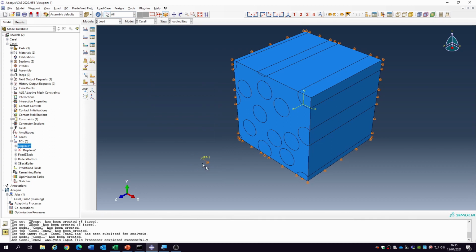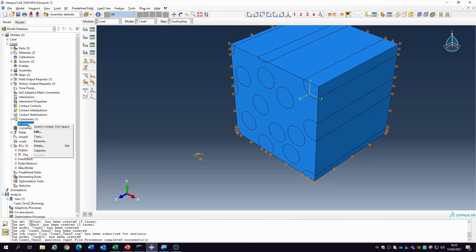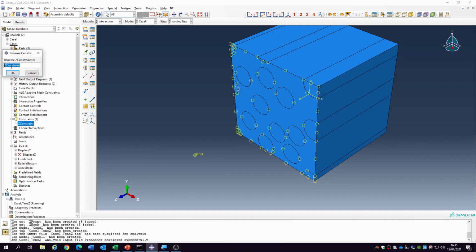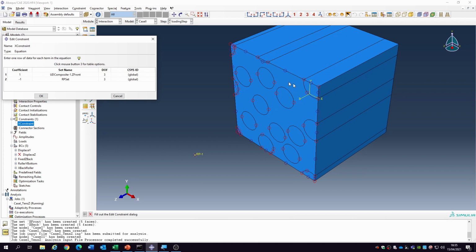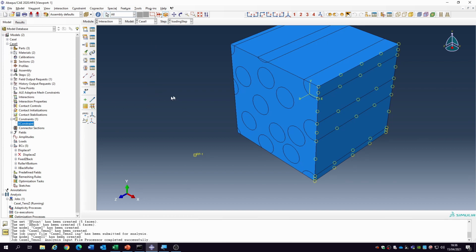So we've got the loading here in the 3 direction, but we also need to change the constraint, because our constraint was constraint Z, so I renamed that and called it a Z constraint, an X constraint, but it's going to move from this face to the face of interest. So instead of the Z front, we are going to do the X front. Instead of being in degree of freedom 3, it will be degree of freedom 1, because this is X. So what has happened is that we've got the loading here translated to what's happening there. Okay, so that gives us the right simulation for that.